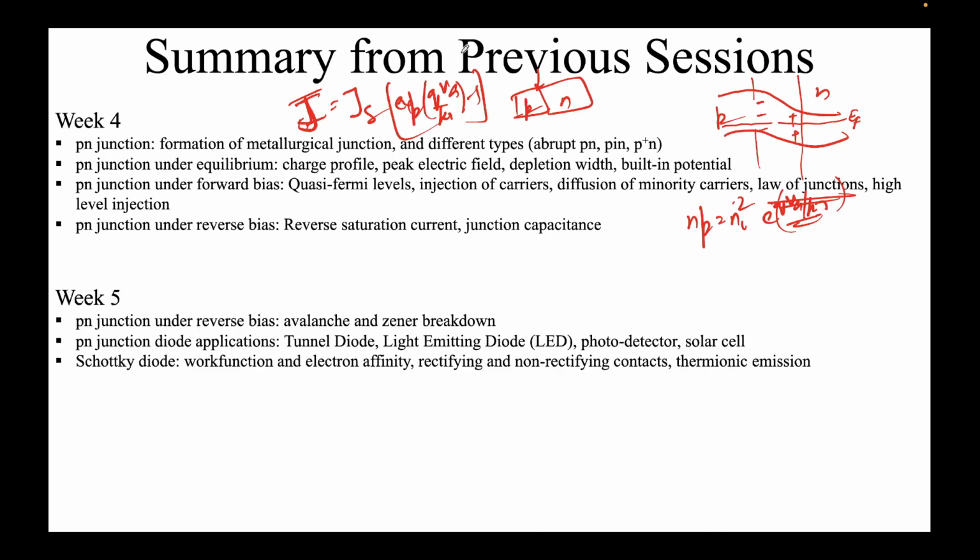We discussed reverse breakdown in more detail in the avalanche, which used to happen, for instance, when the dopings are moderate level and the electrons have to travel a huge distance in the depletion region. Please remember that when it's reverse biased, the depletion region gets widened. So if an electron somehow enters this depletion region, it has to travel across. It can gain sufficient energy that it can knock out other electrons, which can further knock out another series of electrons. With this chain reaction, a huge amount of current can flow. Avalanche.